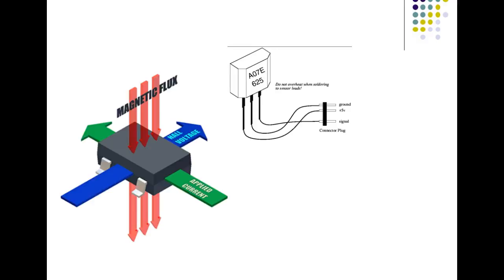It takes at least 2 wires. But these guys have to be powered up. So that means we've got to have power on them. So we have this guy here that powers up on 5 volts, and we have a common. So they either have 4 pins on them or they have 3. We can share a common, and then it's got a signal output. So I'll have to take one of these. I'll have to look this guy up and see if it's a latching.